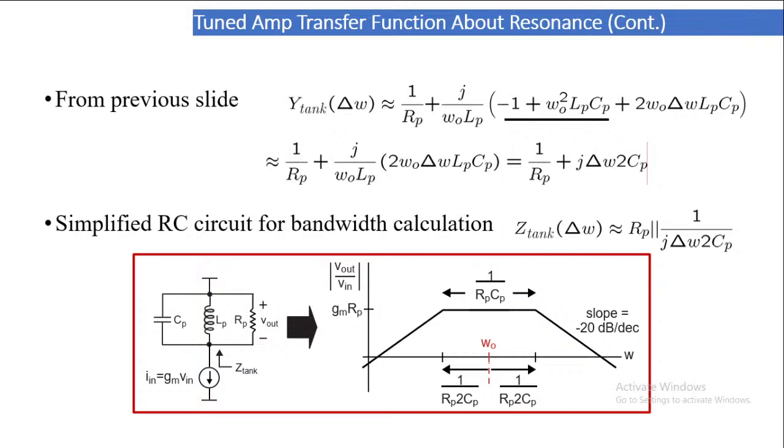When from the peak it is coming to 0, as the gain reduces to 0, the slope is minus 20 dB per decade, which means it decreases by 20 dB for every 10 times the frequency. Which means at the edge, suppose it is F1, then at F1 it is 0 dB, then at 10 F1 it will be minus 20 dB. That is what is meant by minus 20 dB per decade.